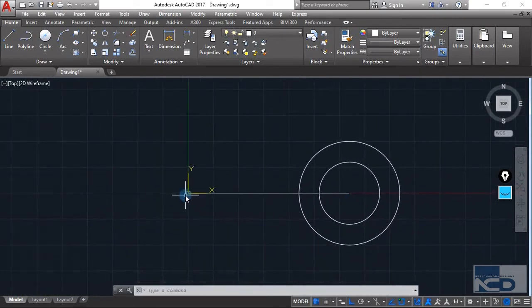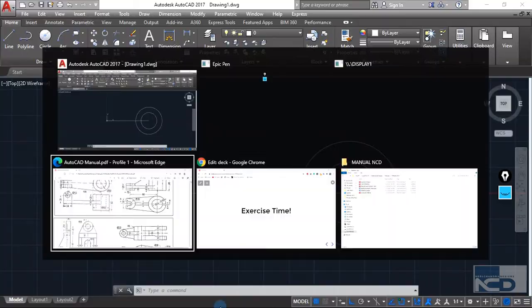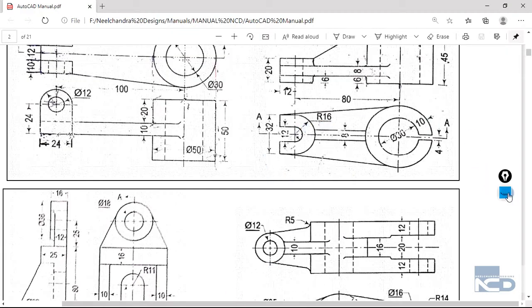Now we have to create this section over here, which is the magnet-like structure. For that also we just have to create two circles, two concentric circles basically. Let me just calculate the values of those circles. So this over here is 12 mm, so this will also be 12. It means that the diameter value of this circle, which is our arc right now, is 12, and the radius value of this bigger circle is given over here, which is 16.